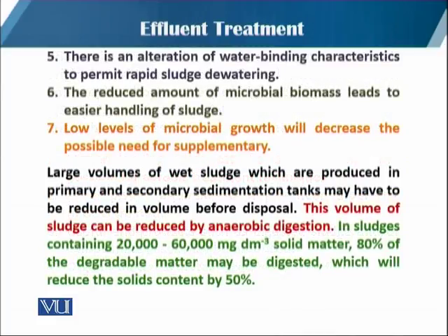Fifth one, there is an alteration of water binding characteristics to permit rapid sludge dewatering. Number 6, the reduced amount of microbial biomass leads to easier handling of the sludge. As concerned number 7, the low level of microbial growth will decrease the possible need for supplementary treatment.